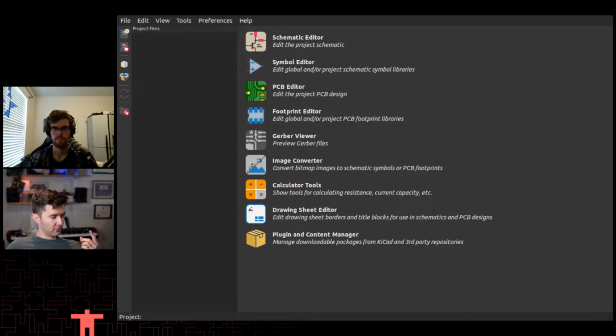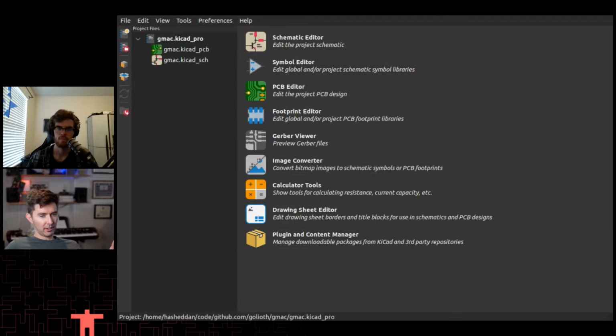Footprints are free. So if you're going to put down 9 keycaps and you think there's any possibility there's some other feature you want to put on there, put that down, but don't populate it, right? You could put down the footprint, but you don't have to necessarily populate that part. You can always add that functionality later. And then two is, you could start bigger and then plan to have a shrink stage in the future.